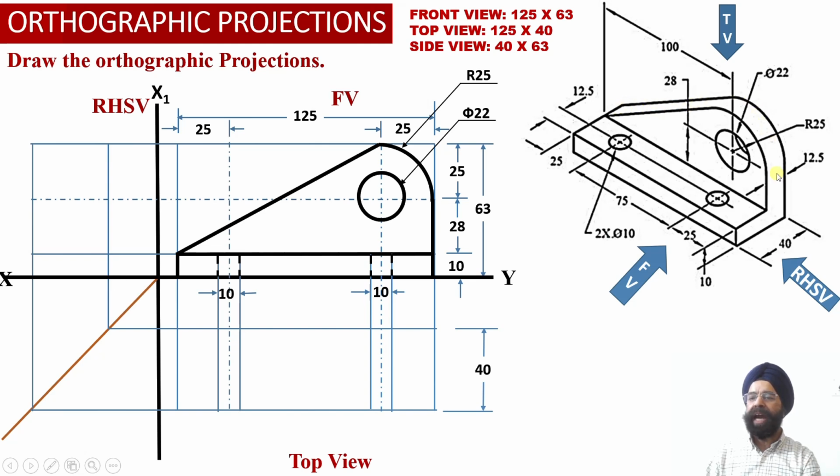And another thing, we know that this vertical web lies towards the rear surface of the solid over here. So this is the rear surface of the solid, this is the front surface of the solid. So on the rear side of the solid, we have measured a distance of 12.5 millimeter corresponding to the depth of this web, and we have drawn a horizontal projector line at a distance of 12.5 millimeter from the rear surface. And this horizontal projector line we have appropriately transferred into the right hand side view projections over here using this transfer line.